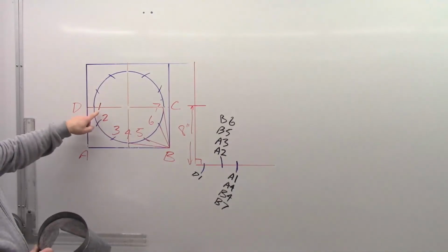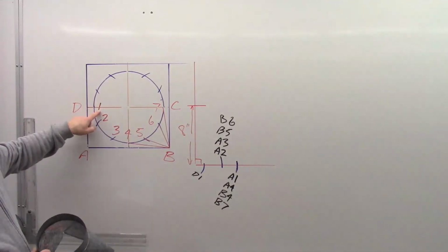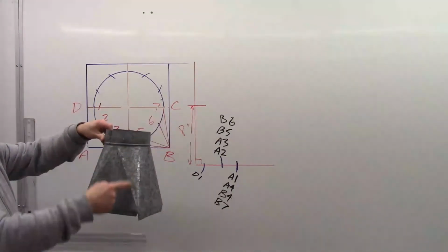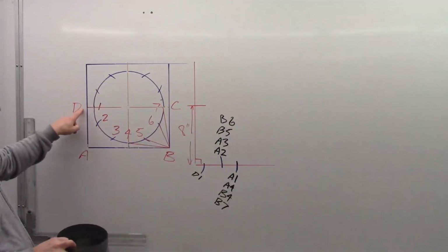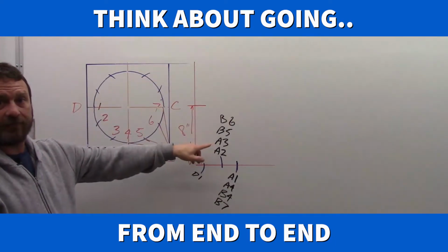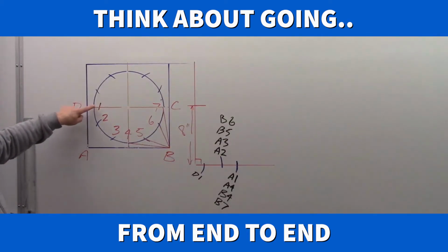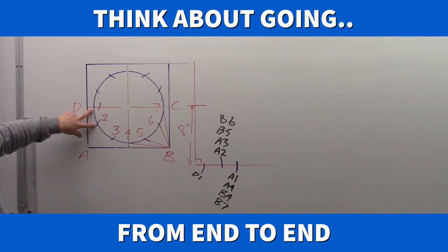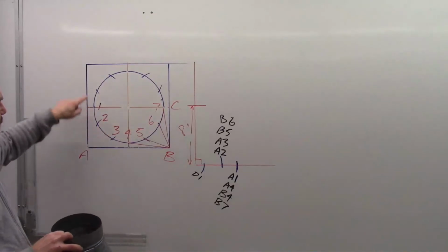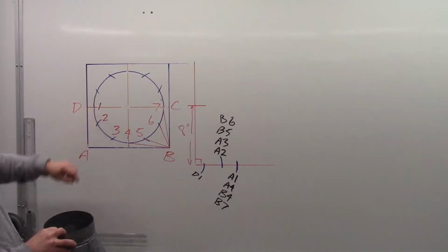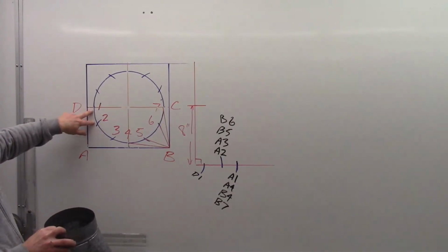But what we do know is going from a number to a letter, we're going from one end to the other in some way, some fashion. So anytime we're going number to letter, true length diagram. Okay? If we're going number to number, that's a true length. That's one of our step-offs. This truly is the circumference of an 8-inch diameter, and that's 1/12 of that circumference. That's a true length. So number to number is a true length in the plan view.